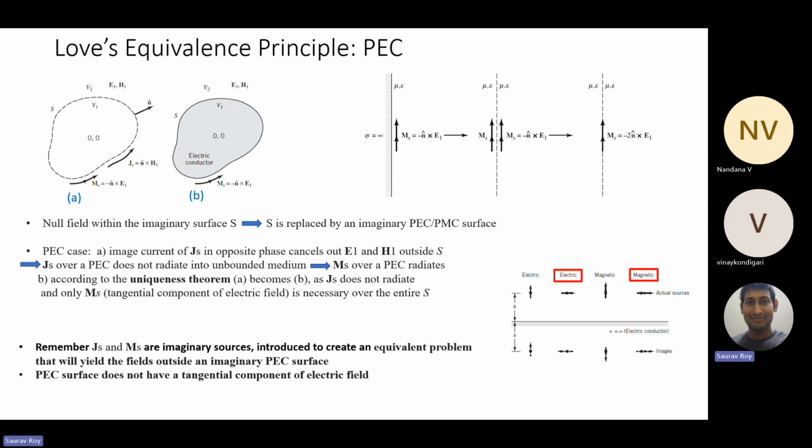Generally, all this we use for aperture antennas. Aperture antennas are mostly like horn antennas and patch antennas. That means it has some area in the surface, not like a dipole antenna, not like one wire. Aperture means it has some area surface, right? Just like a horn antenna, on all four sides there are metals, PEC. In the outer layer we have an open surface, like a waveguide opening. So the horn has metal on all four sides, and in the front it is an air opening.